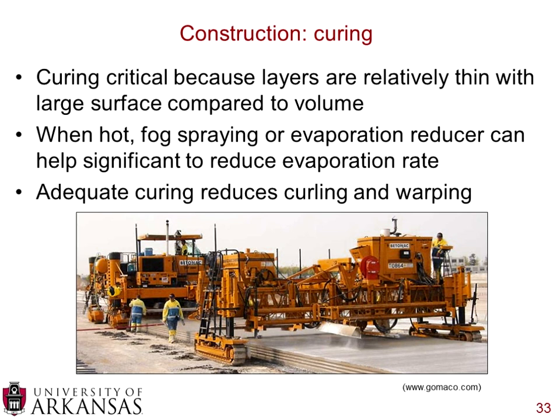So if it's very hot, you can fog spray an evaporation reducer, or you can put some sort of sealant on. And that's what you see there in the picture below. You have your slip form paver going away from you in the background, and in the foreground you have a machine that's spraying a curing agent on top to make sure that water doesn't evaporate.